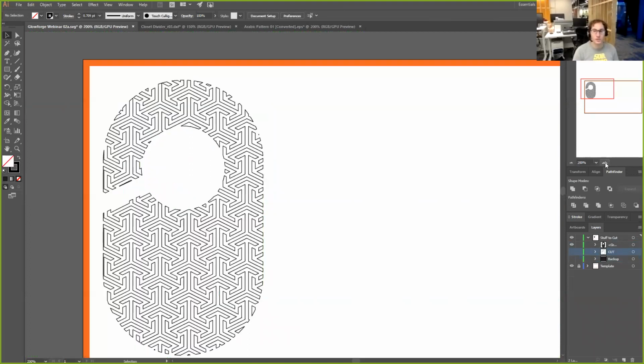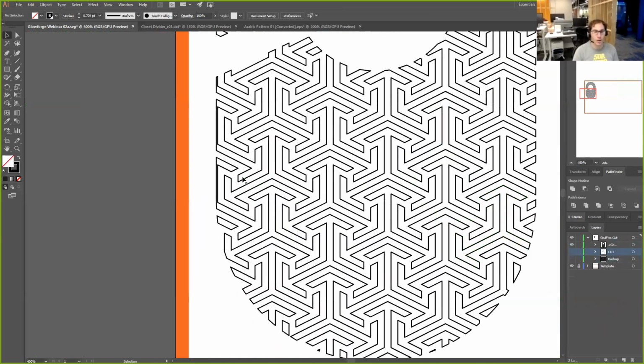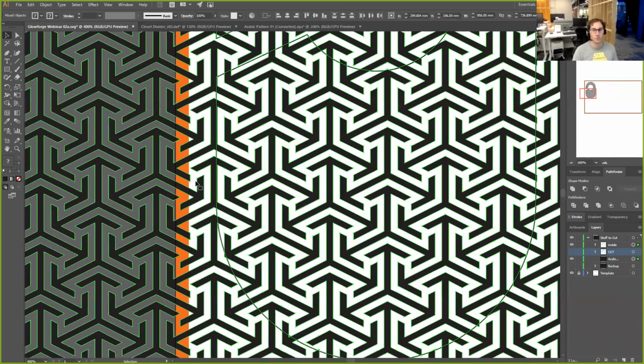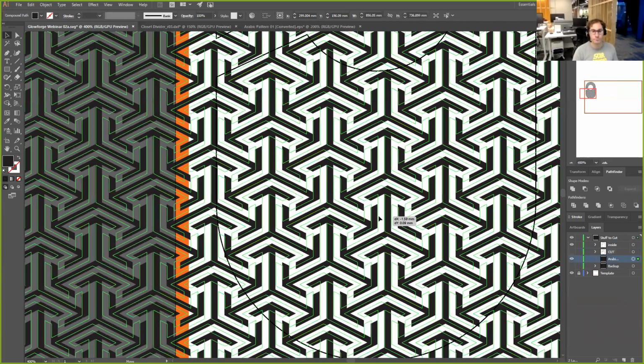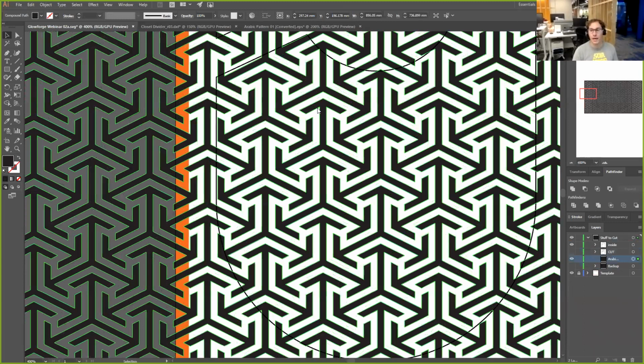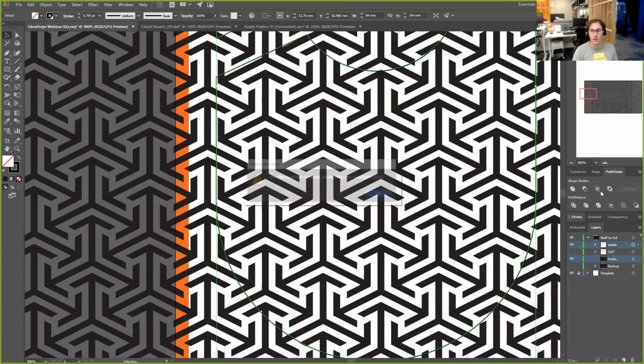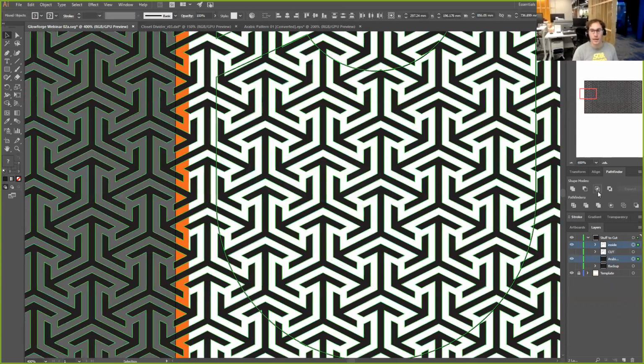And again, if I zoom in here, I'm seeing something weird going on over there. These paths are a little too close. So again, I have to undo, move my pattern. Directly inside of Fusion, I don't have to leave this environment. Perfect. And then again, choose the inside and say I want to intersect. Over from the model workspace. And I didn't select two things. Let's try that again. Workspace. Intersect. It changes my ribbon bar, and it changes my browser.